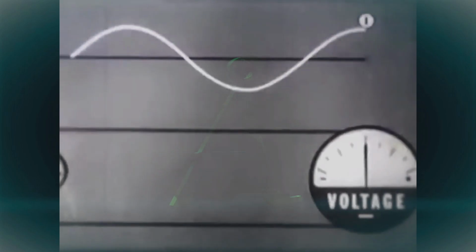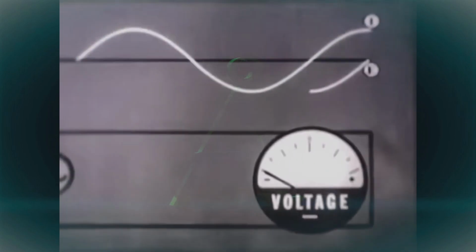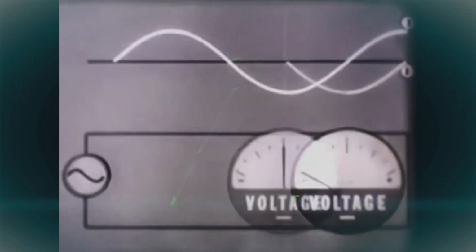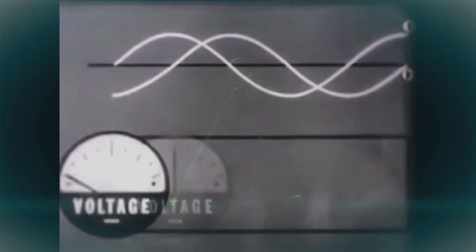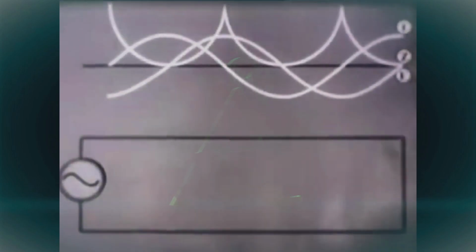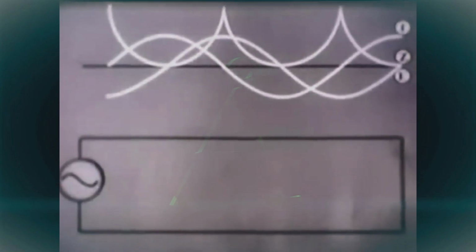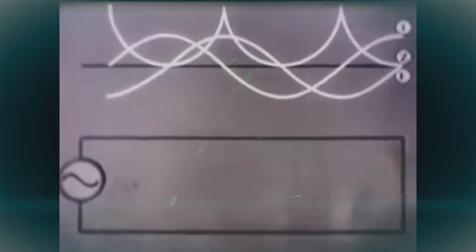The voltage at the closed end of the line is, of course, at minimum value. 1/4 wavelength down, the voltage reaches its peak, and so on to complete the standing wave of voltage. Impedance is minimum at the shorted end of the line. According to Ohm's law, when current is maximum and voltage minimum, the impedance is minimum.